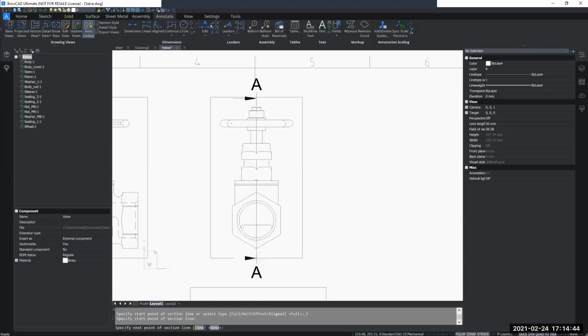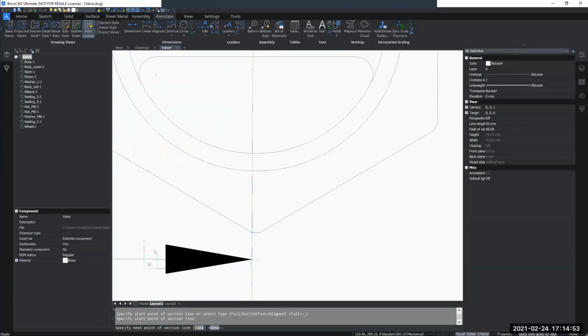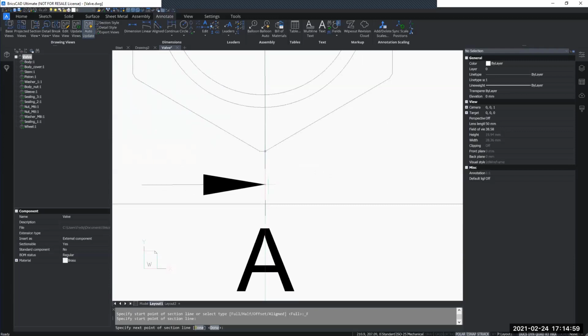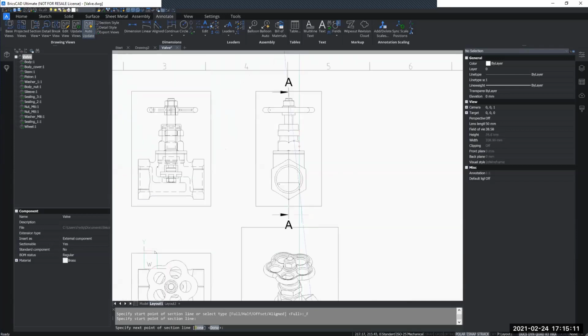Now I want to place it on the bottom here. You can see it kind of snapping onto a lot of different parts here. And maybe I accidentally track the wrong part down here since there are different snapping options. To avoid this, I can hold my shift key and you can see it stays on this certain axis no matter where I move my cursor next to it.